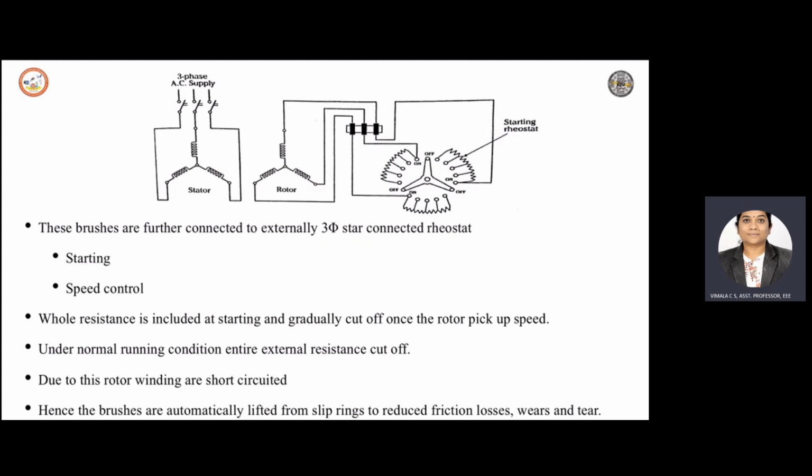The whole resistance is included at the starting to limit the initial starting current, the inrush current, because normally an induction motor without load draws more current, 5 to 8 times the normal current, which might damage the induction motor because it is short circuited sometimes, or it can damage the supply or the devices connected to the induction motor.